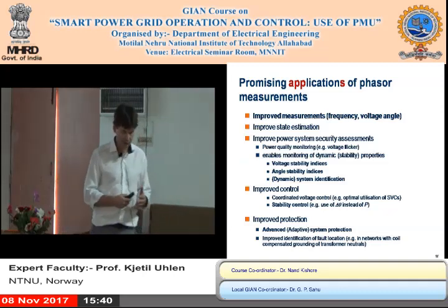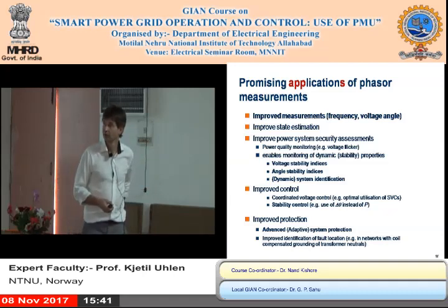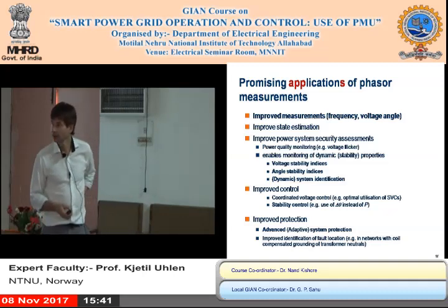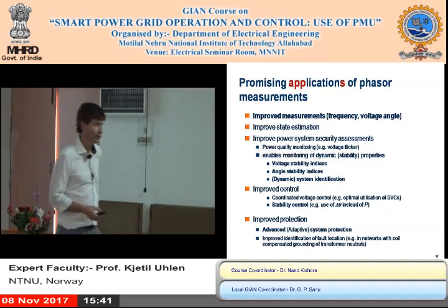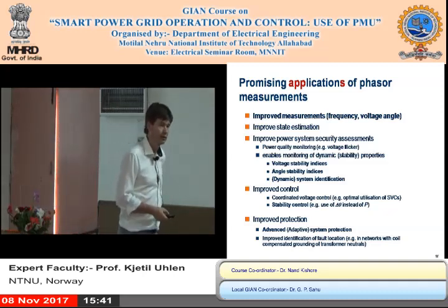That's usually the solution to a power flow: the voltage magnitude and angle. So if you have good data for your lines and parameters, and you have full coverage of PMUs, you don't need to estimate the state any longer. You can just measure it.